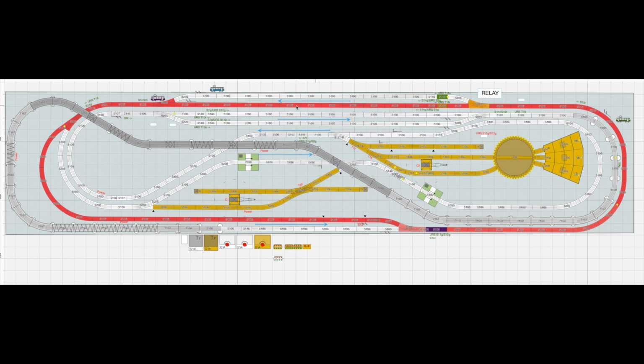And the green train will then carry on to wait at the signal behind the station. The purple train will go over a contact track, set the signals behind it back to red, then reach the next switching track, which will release the train waiting in the block before the station.